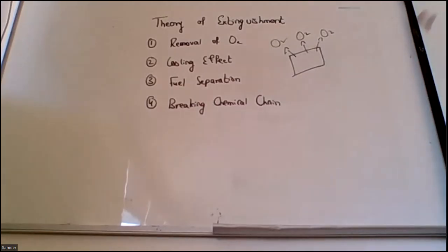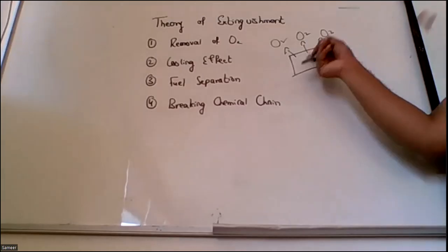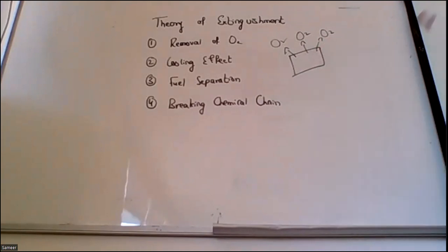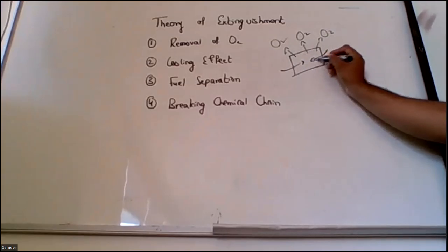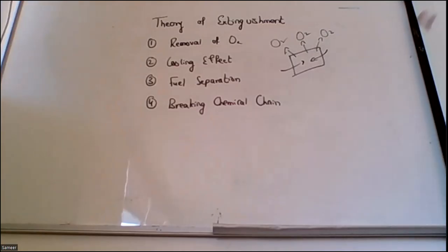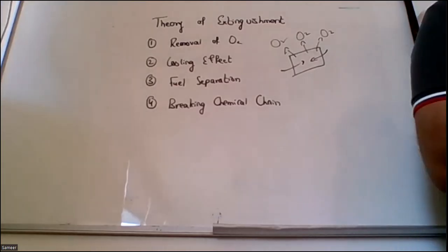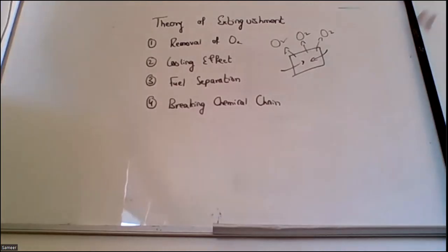The flame will disappear, but again, the flame will reappear. Why? Because carbon dioxide is a surface-based extinguishment, but this oxygen is coming from inside the metal itself, from the chemical itself. So I need to actually break the chemical chain reaction within the chemical itself, so that this free release of oxygen is not available. Basically, this is the chemical chain break reaction that we want to do. We want to convert the oxygen that is being produced from within the material itself, fertilizers, into a product that will help me in creating extinguishment.